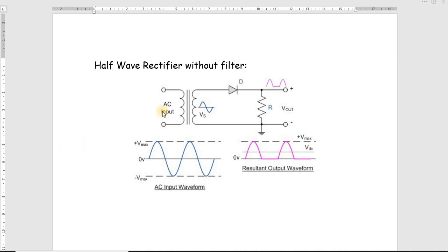The step-down transformer consists of a primary winding and a secondary winding. Here the number of turns of the primary will be higher than the secondary. When the primary winding is supplied by an alternating source, the winding gets excited, so flux is created. The secondary winding experiences an alternating flux because of the primary winding, so the induced EMF flows through the external circuit and produces an output. Here is the corresponding stepped-down alternating current source.